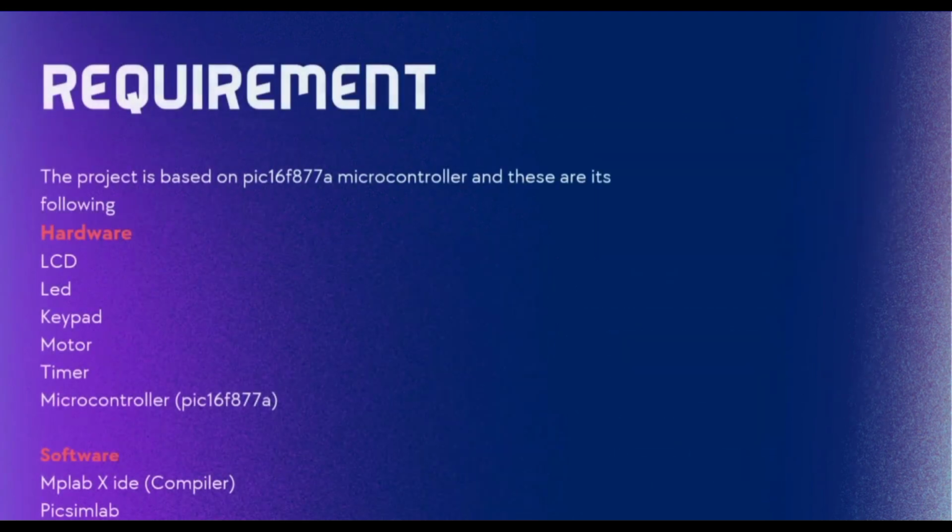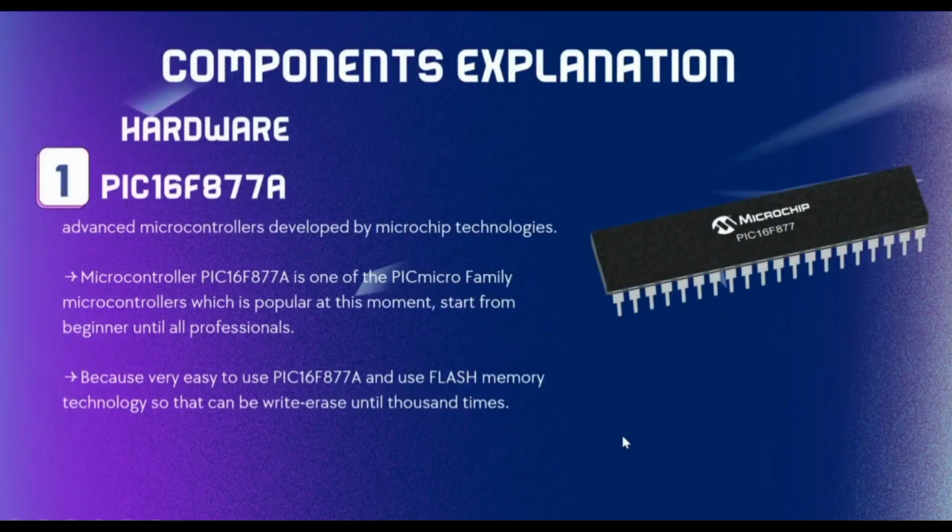So, the requirements of the washing machine are hardware like LCD, LED, keypad, motor, timer, and microcontroller, and software like MPLAB XIDE, compiler, and PICsimLab. This product is based on the PIC16F877A microcontroller.